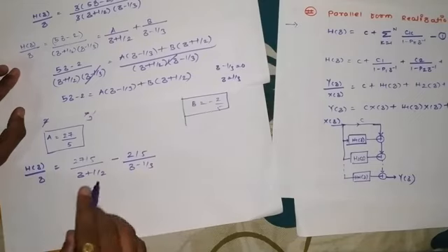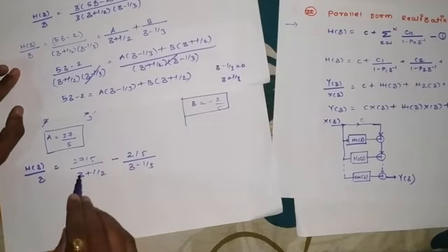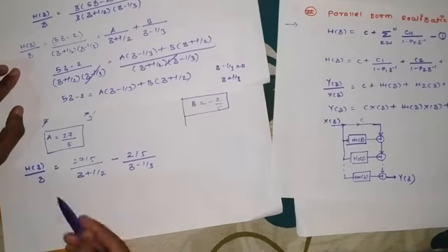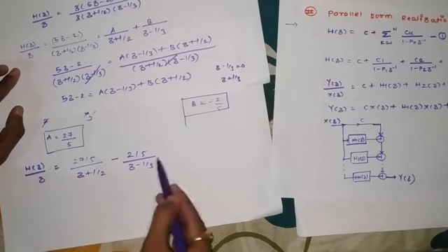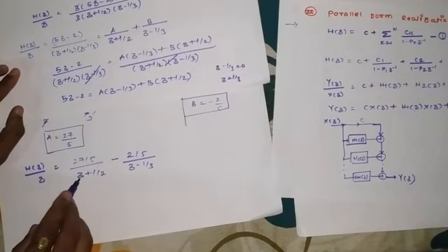Now in order to realize this using direct form 2 realization, we need a delay element, that is z inverse. So one has to obtain all these terms in the form of z inverse. That may be possible if I divide this entire equation by z. You can see if I divide this by z, this z will get cancelled. Similarly this one will get cancelled.